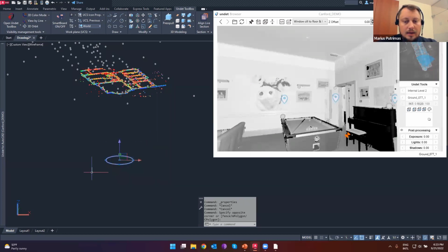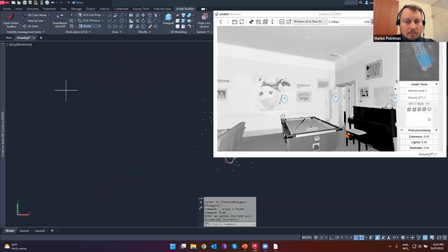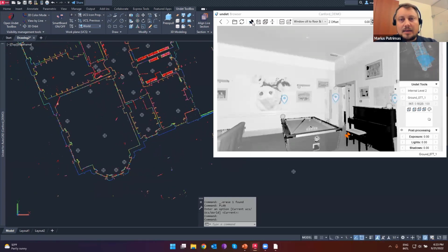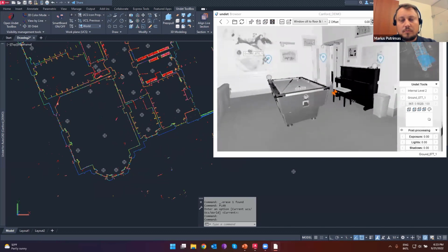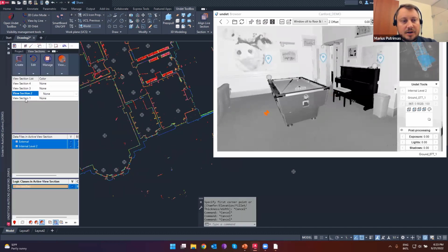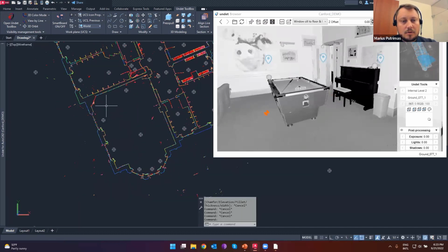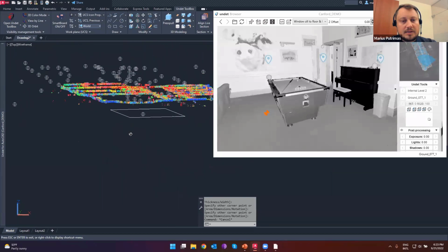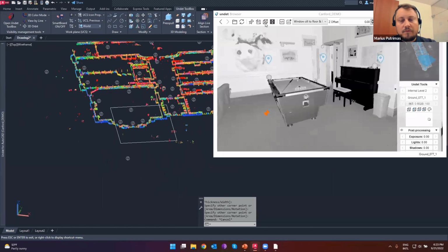And again, I am now getting back to a plan view, selecting feature, change elevation, clicking on these floors. And now if I will draw this rectangle or circle, doesn't matter. And if I will rotate, you will see it will be placed on my floor level.